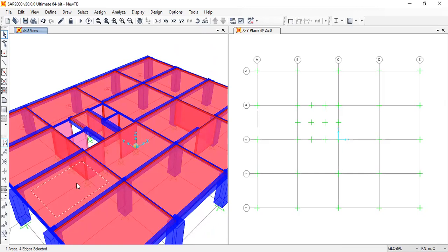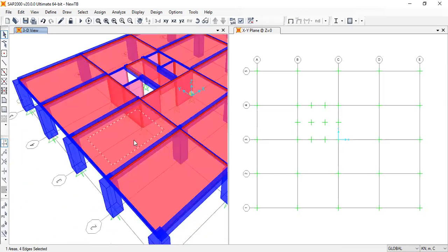So we have already distributed the loads to the beams, right? So we don't need the slab to transfer the loads, but the problem is the slab should now have the mass, as you already know for the modal mass, right? So at the floor level, they should count the mass of the slab, right? So here's how we are doing the trick.